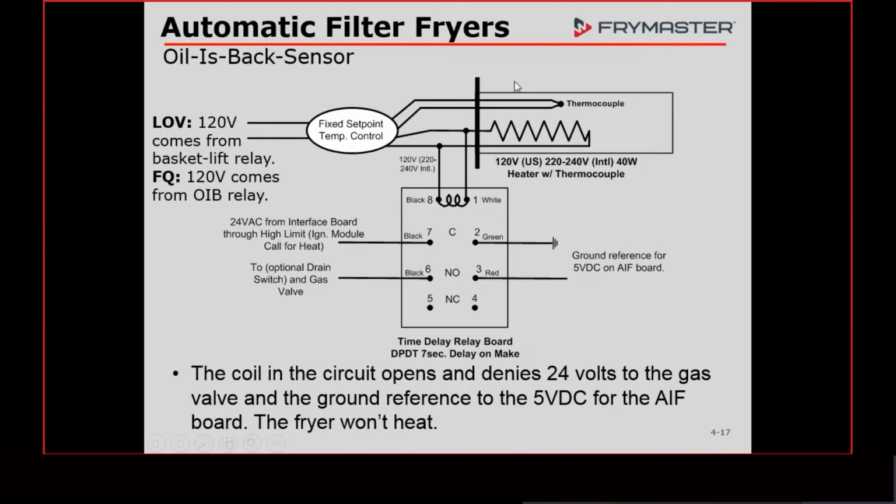We have the part that goes into the fry pot, which is just a heater. This is a submersible heater that is set at one temperature. That temperature, I don't know, it's over 500 degrees, 500 or better. You know, because we used to say 550. You're like, no, it's only 500. It really doesn't matter. It's more than 350 or 375, which is our highest set temp that we want anybody to use the fryers at. But it is a heater. For the sake of discussion, we're going to say 550. It is a heater that is set at 550 degrees.